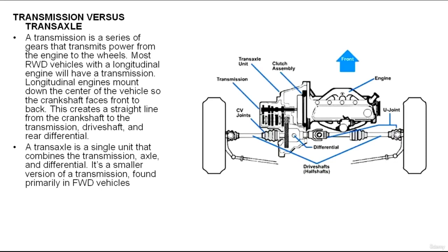Most manual transmissions and transaxles are constant mesh, fully synchronized units. Constant mesh means that whether or not the gear is locked to the output shaft, it's in mesh with its counter gear. All gears rotate in the transmission except for reverse gear, as long as the clutch is engaged. Fully synchronized means that the unit uses mechanisms of rings and clutches to bring rotating shafts and gears to the same speed before shifts occur, and this promotes smooth shifting.